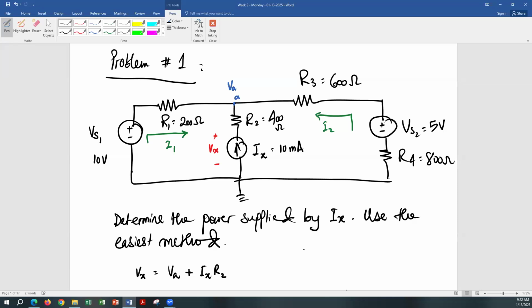Would there be a difference in the voltage drop? No, remember, again, it's the same current. However you rearrange components in a branch, it is still carrying the same current. So from ground to VA, that's the same voltage if you calculate through that branch. VA is not changing, and the other end of that branch is grounded. So when you go around that branch, the total voltage in that branch adds up to VA, irrespective of how you arrange those components, right?